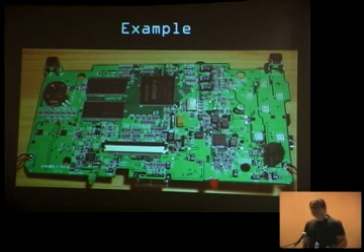Next one. Have you ever seen a manufacturer etch the number labels off the chips? Oh yeah. To make it harder for the engineer? Yeah, I think they do that all the time when they're paranoid. What do you do when that happens, to find out what the chip actually is? Well, a lot of times when they do that, they think they have some secret sauce. One thing they'll do, which is a mistake, is etch only the part that they don't want you to find out. So there's one part with something etched off, and you say, okay, this has got to be the memory or the processor, so I'm going to start attacking that first.